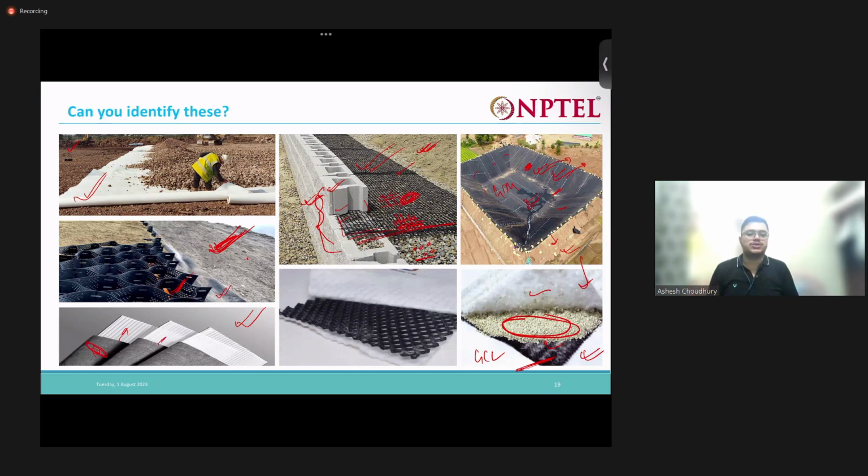This PVD actually accelerates the drainage of water in a soil. So what will happen if the drainage path is reduced and the drainage of water is accelerated? It will accelerate the consolidation process, right? Yes, if the drainage path is reduced, the consolidation process will be accelerated.